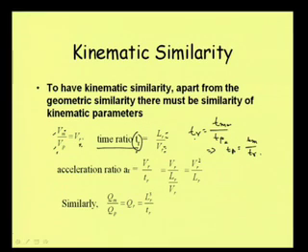And well, with the same idea, if we try to get acceleration, say we write it as acceleration ratio, we can get the velocity ratio divided by time ratio, and if we simplify, it becomes velocity ratio square divided by the length ratio. Well, because time ratio we are replacing by LR by VR. So, we are getting this expression.